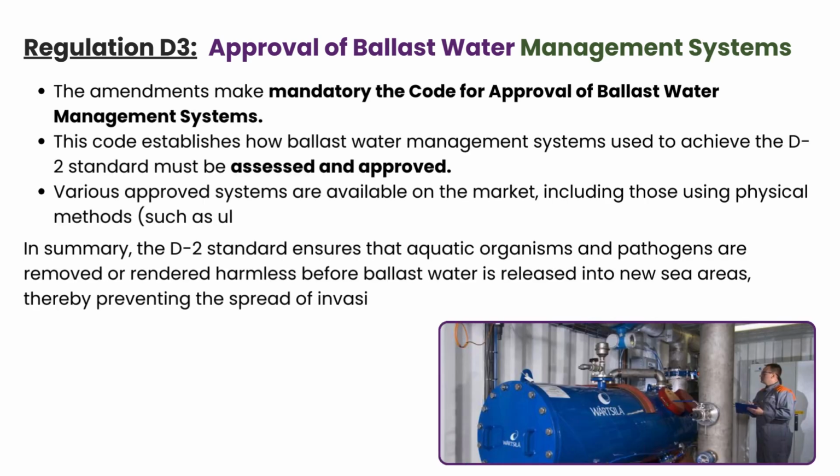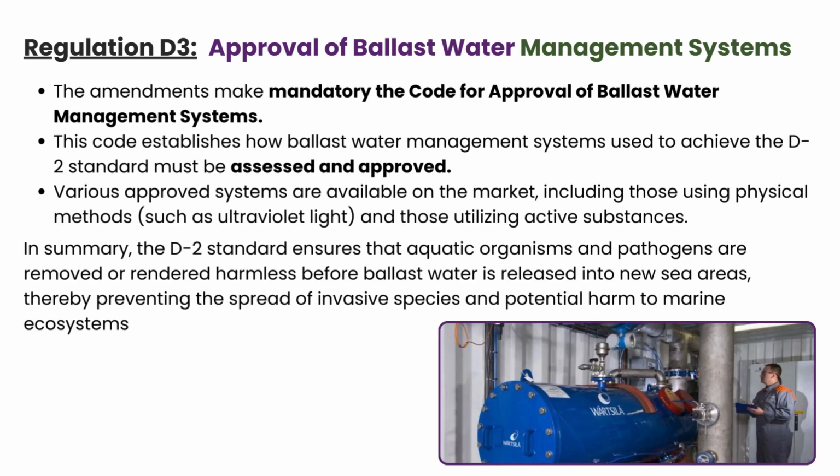The next requirement is to have an approved ballast water management system. The approval has to be done by a classification society or a standard body as accepted by the flag state. This code establishes how a ballast water management system achieves the D2 standard, and also tells how it has to be assessed and approved.